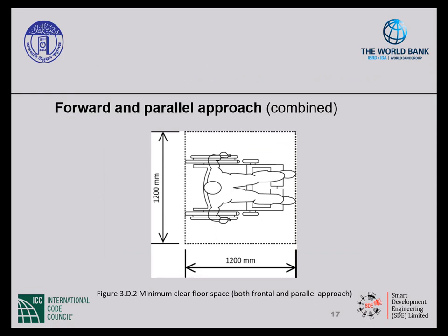To facilitate both parallel and forward approaches for wheelchair users, a minimum clear floor space of 1200 by 1200 millimeters is provided as shown on the slide.